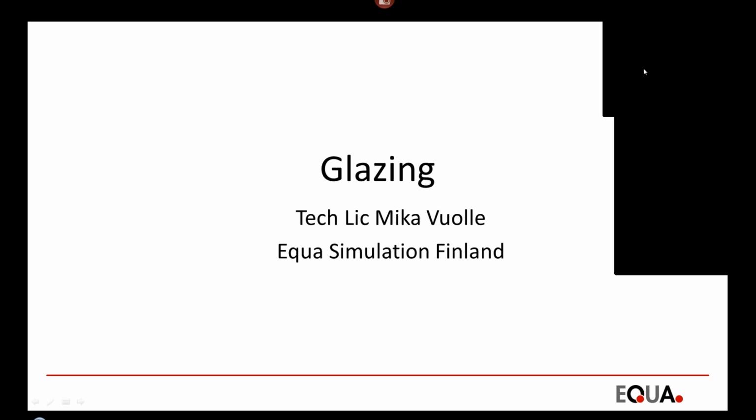Okay, welcome everybody. I have used the phrase a lot that the window is one of the most important components in the building. It has a major influence on lots of things. For example, it has thermal conduction, the U value is rather high, so it has high losses and a big impact on the thermal losses of the envelope. Daylight, cooling load, visual comfort, and etc.